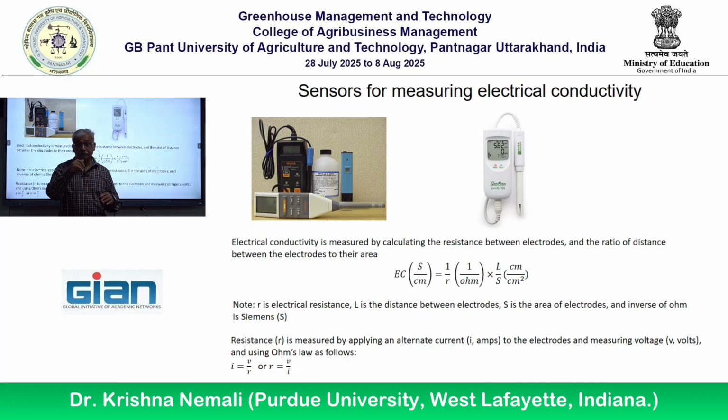But when you are making a measurement at, let's say, 30 degrees Celsius, then you get a higher value than what is exact. It's confounding basically. The temperature is confounding it, and you are getting a wrong number simply because the water temperature is higher than what the company originally did the calibration for.